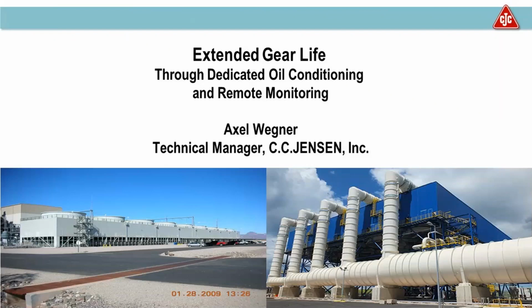And under normal circumstances, if there is no accident, you will only change those filter inserts once a year. And the cost, in this small size, you're looking at maybe something like $120 per gearbox per year for the filter insert.